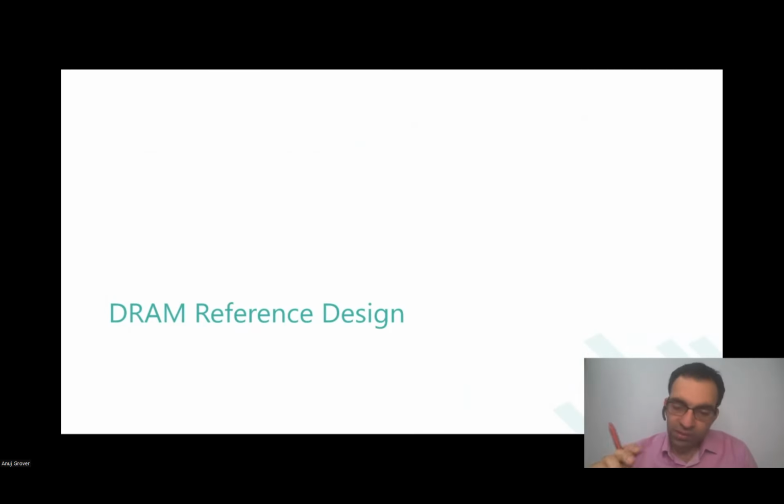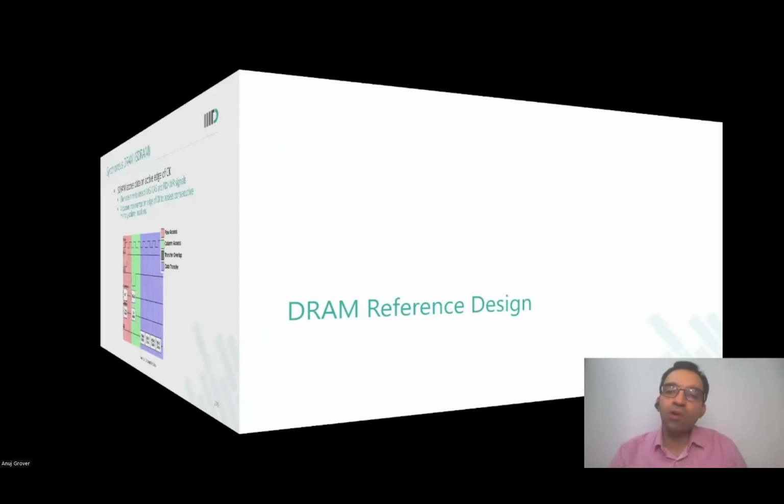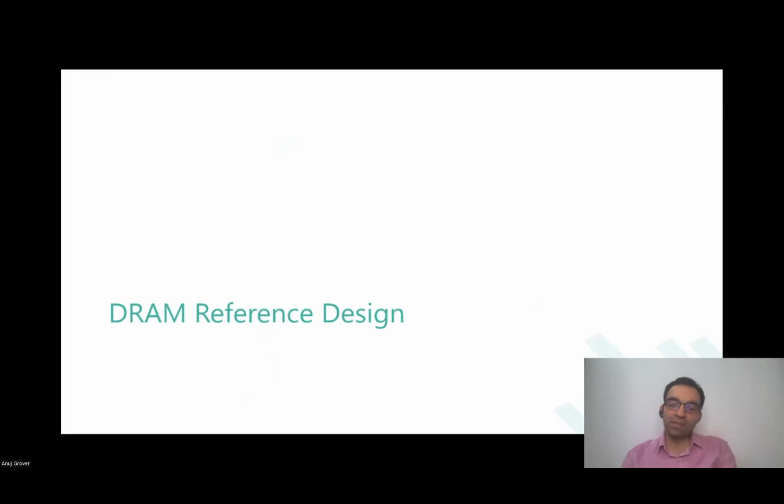So now with the speed aspect taken care of, we look at how to design the reference. The question that came earlier in the class was that the bit cell has only one bit line. How do you get the reference bit line?